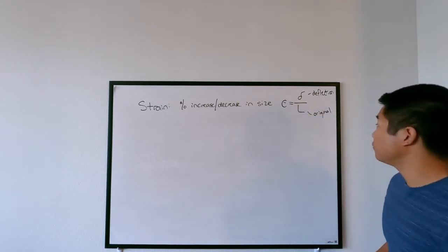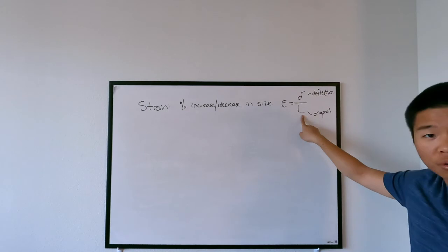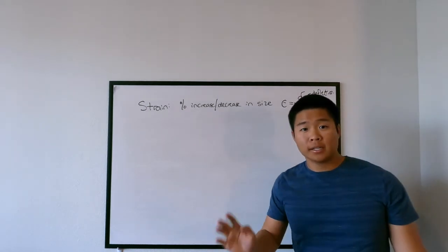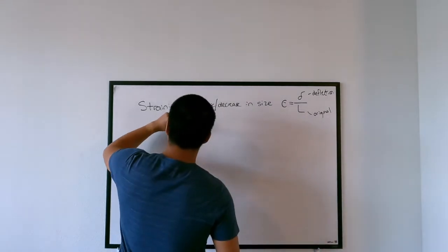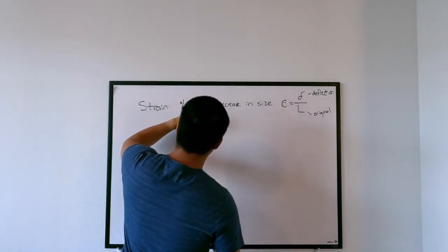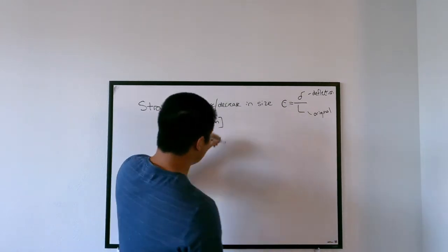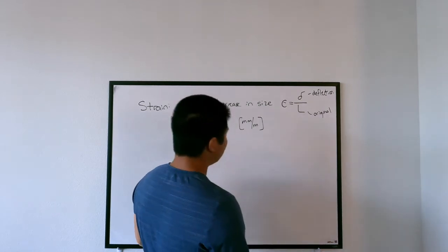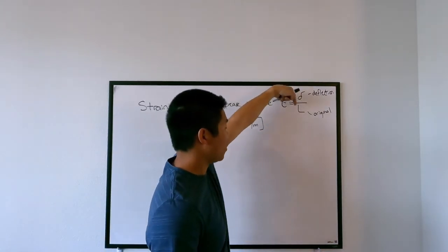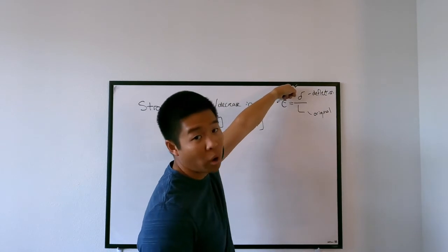Of course, the deflection and the original length have the exact same units, so therefore our strain epsilon is unitless, or sometimes we call it millimeters over millimeters. Other times you'll see it as millimeters over meters, okay, which says like, oh, a 1 meter long stick got compressed by 1 millimeter.